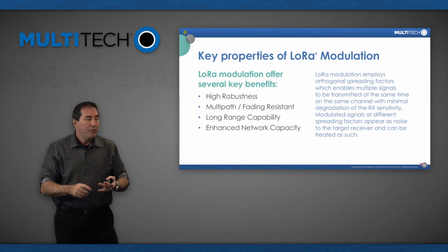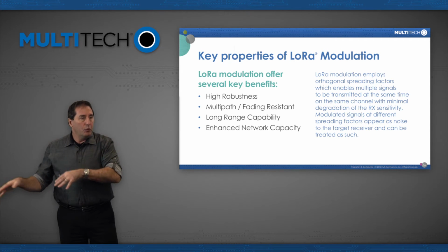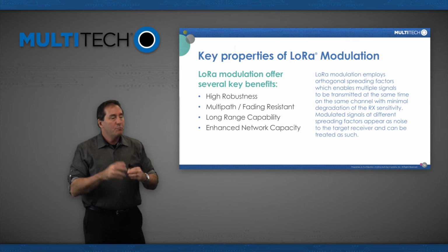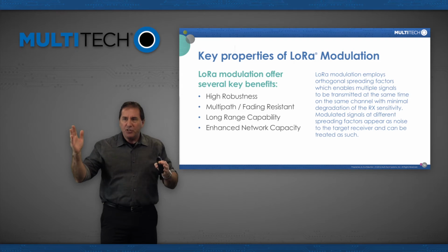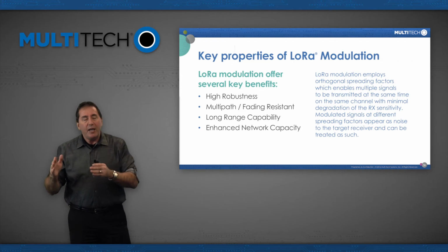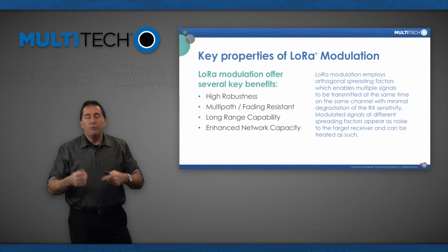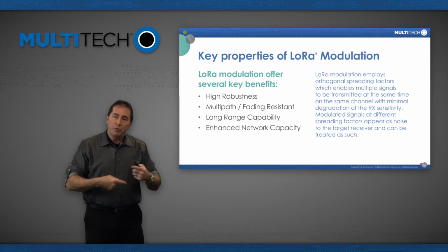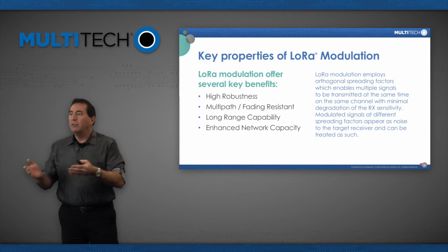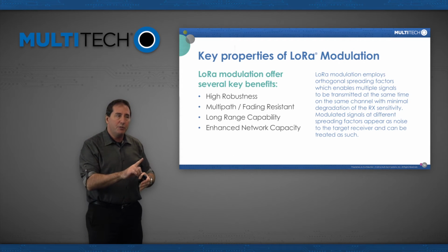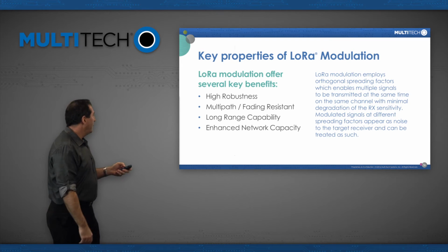In addition, there's not an equal distribution of data rates in any given LoRa network. Most endpoints will talk at data rate 7, which is the fastest data rate, and only if you can't get through at that rate does it start dropping you down to a slower data rate. The net result is you get more than 18% capacity. Different models will give you different numbers, but significantly more. So if you hear from customers, oh, it's an Aloha network, it's 18%, you say, not really, okay?